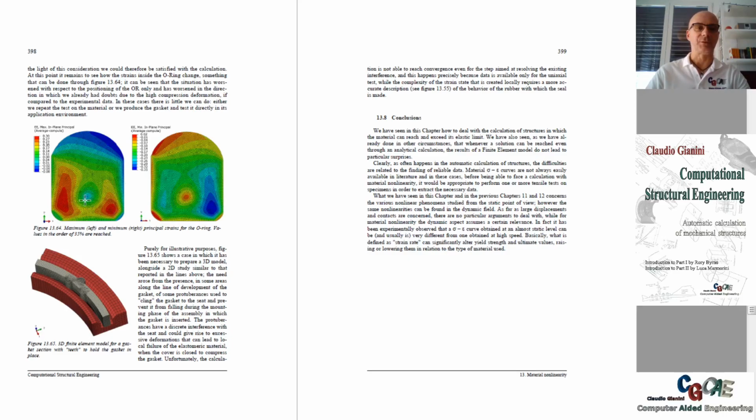When we have elastomeric material and we need to go into a 3D model, things start to be a little bit challenging, because the mesh size needed for the hyperelastic elements is quite fine, and a 3D model will generate a huge number of degrees of freedom, and on top of that the nonlinearity due to the huge deformation of the parts will make the thing difficult to solve. But we will see how this problem might be overcome in some cases.